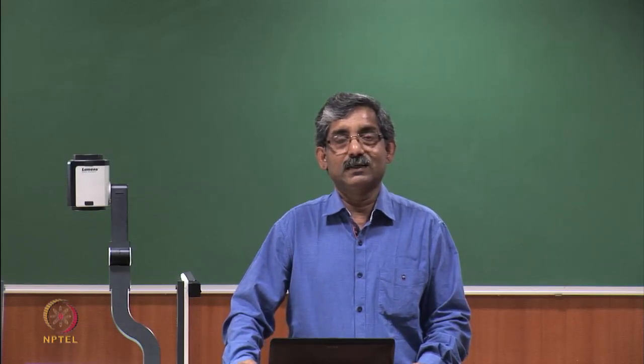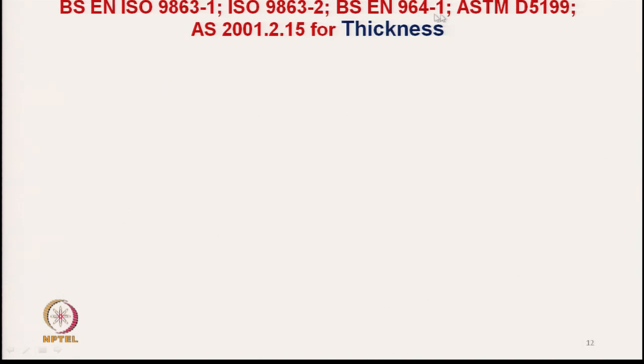Next is the thickness. So, we can use all these methods like BS EN ISO 9863-1, ISO 9863-2, BS EN 964-1, ASTM D 5199, Australian standard AS 2001.2.15. So, any of the methods we can follow.